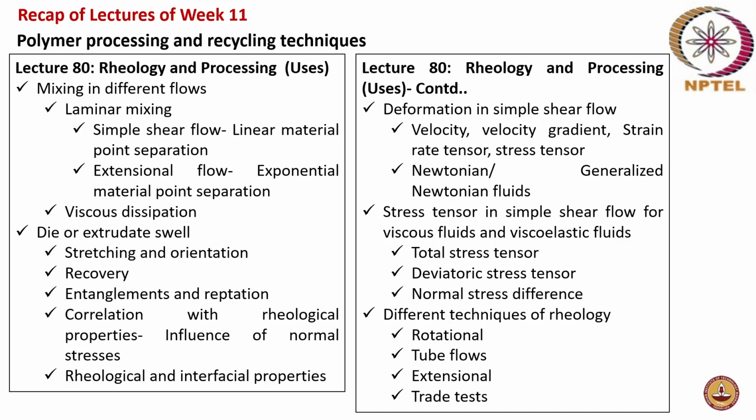Okay, and then viscous dissipation was discussed, and then die or extrudate swelling, because this happens because of the stretching and orientation when it passes through the die, and once it comes out of the die to the outside, there is a recovery and recoiling. So this causes a die or extrudate swell.